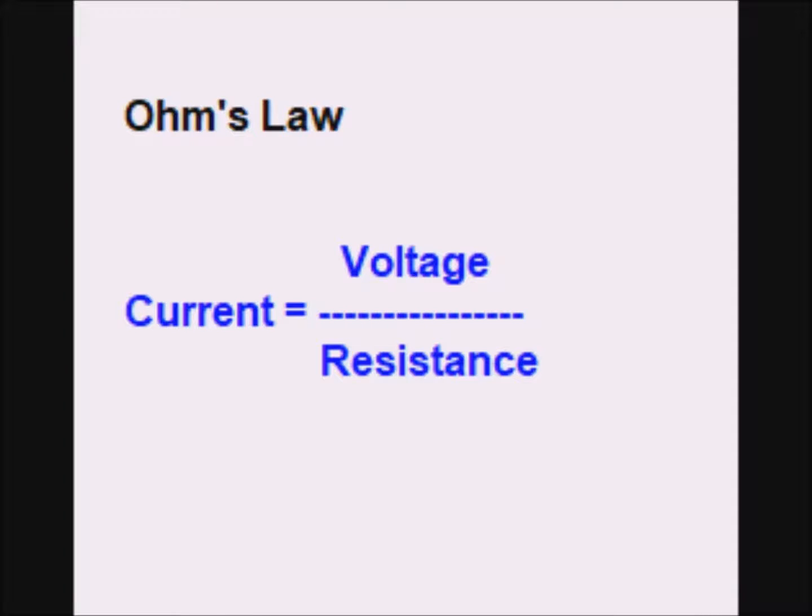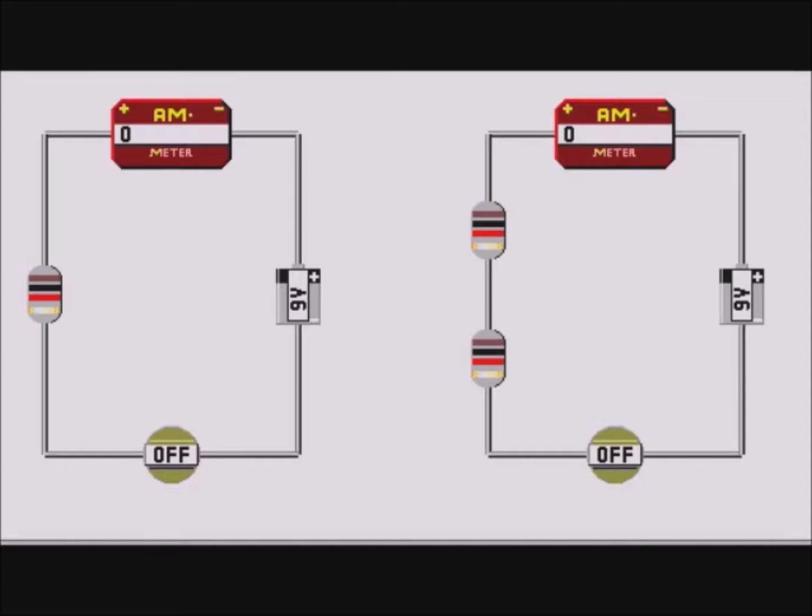We concluded part 1 with Ohm's law. Using the simulator, you can verify Ohm's law for a variety of voltages and resistance, or you can try it out with real components if you have them. Let us compare a circuit with a single 1K ohm resistor with a circuit containing two 1K ohm resistors in series. In series simply means in line. We would expect that if one resistor restricts the current, then two similar resistors would restrict the current doubly.